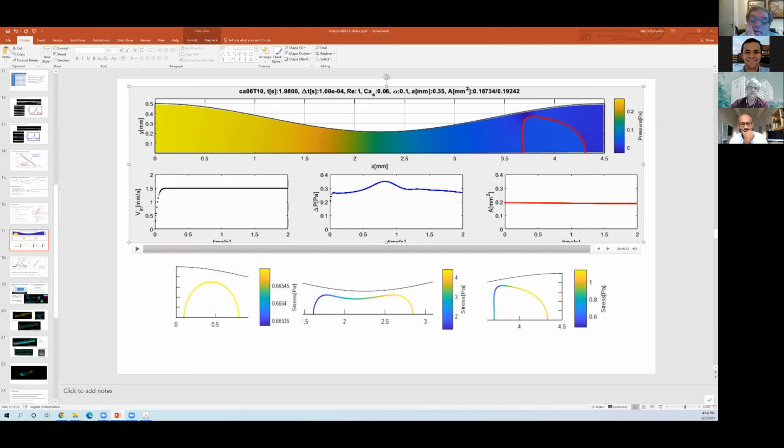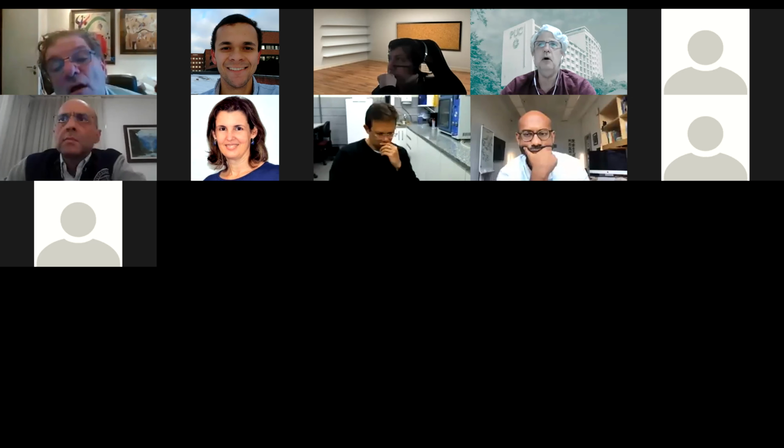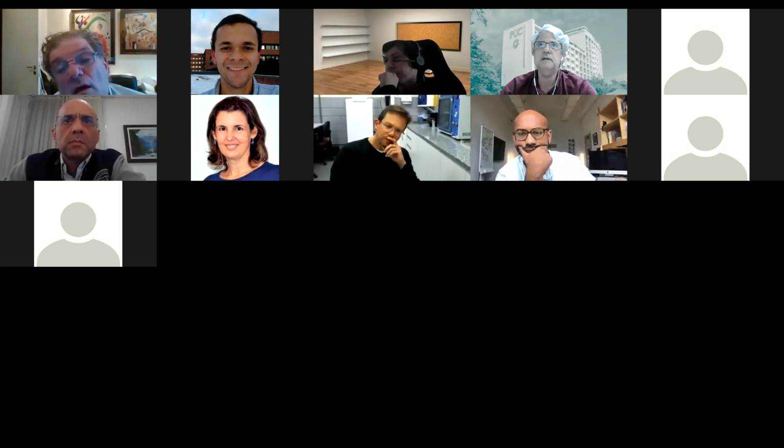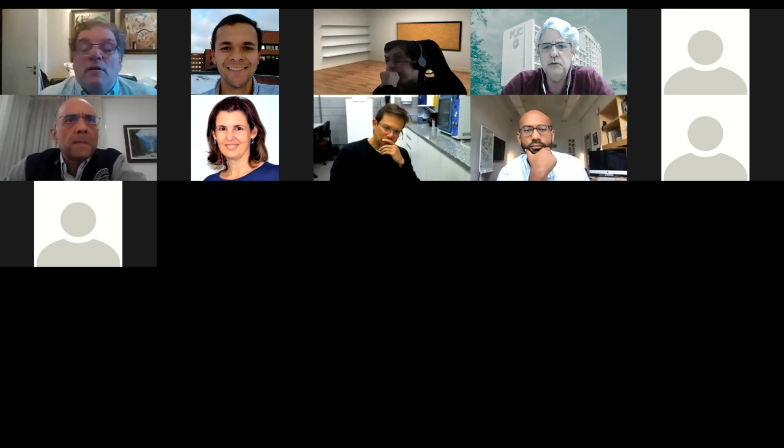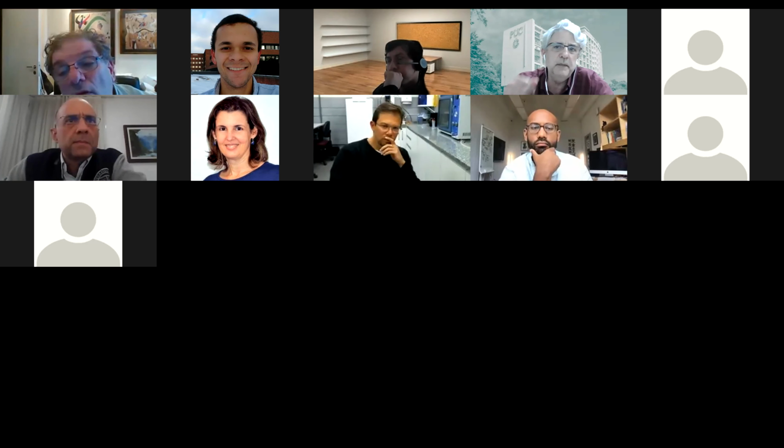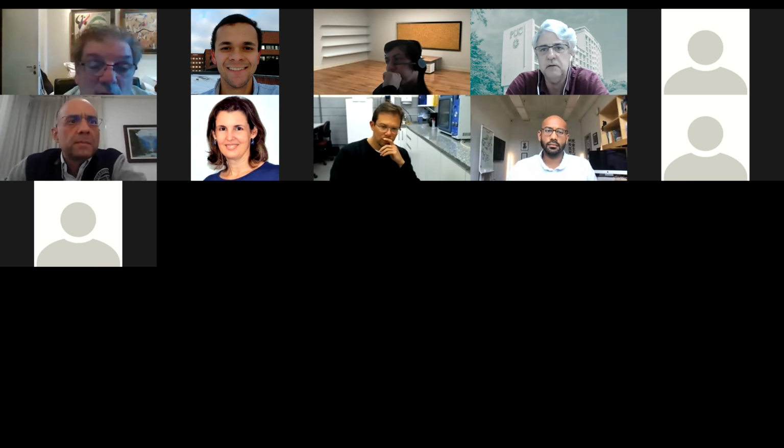Okay, got it. And these shell equations you are solving, they are in very large strains? So we use three different models. We started with just a simple Hookean model, which is probably not valid for the level of deformation. Then we used a neo-Hookean model. We also used what's called a Skalak model, which is good to mimic cell behavior, cell membrane behavior, and things like that. So we tested these three models.